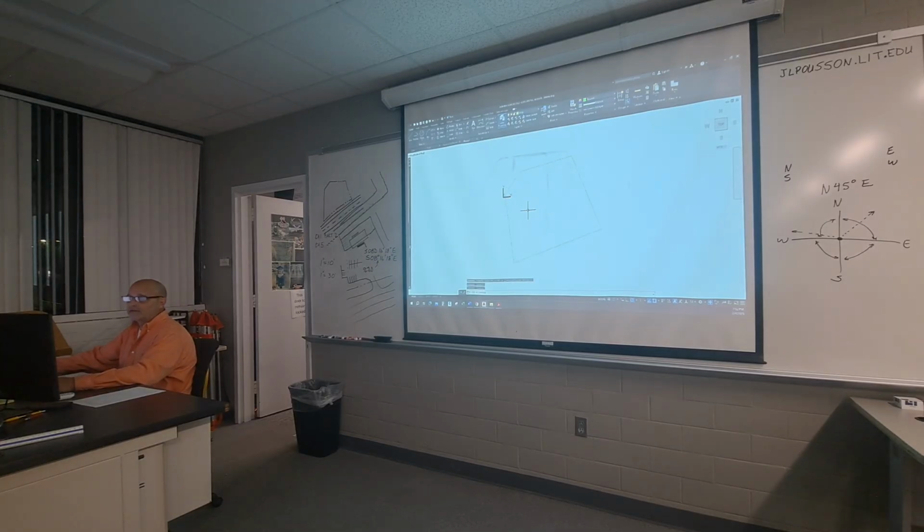Back to my drawing. So now I can explode it, do my offsetting for my property line, for my, I could offset for my easement first, probably would have been better. But for my road, I can offset that, I can click on it, like that's what I told you I usually do. Scale 1.25, something like that to get it outside the property line. And then offset 15 feet.